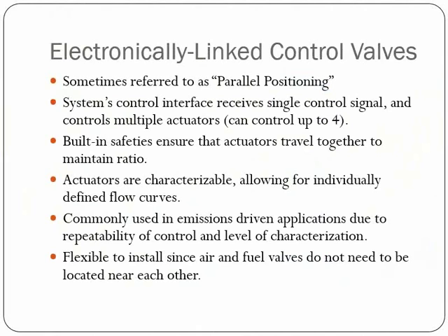As the valves move up and down, they may stray apart from each other, and with extremely sensitive emissions-driven applications, even the smallest hysteresis could cause a system to go from being in compliance to not being in compliance. This also gives you a good amount of flexibility. Since the air valves and the fuel valves do not need to be located next to each other, it's just wiring between them. You can install these wherever you want.